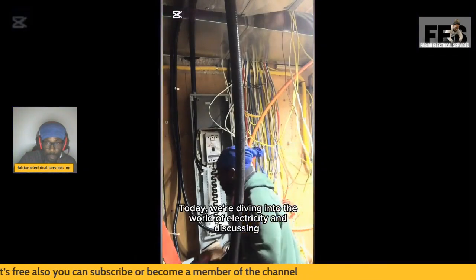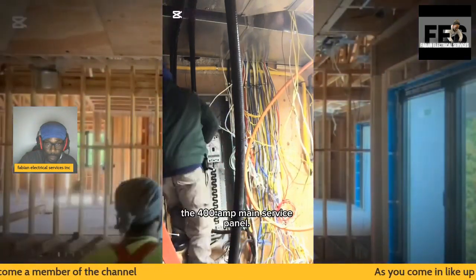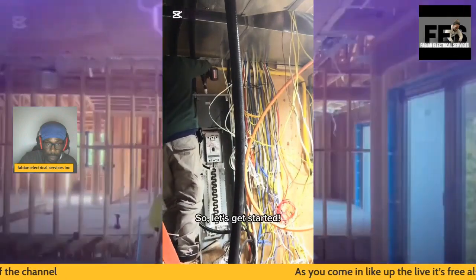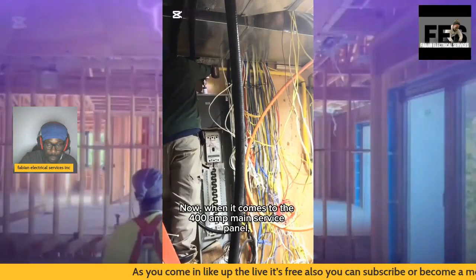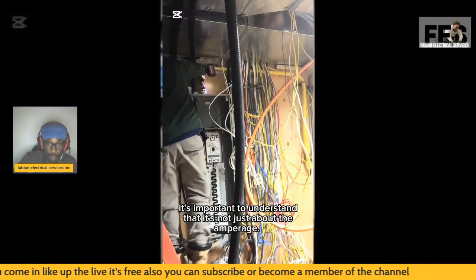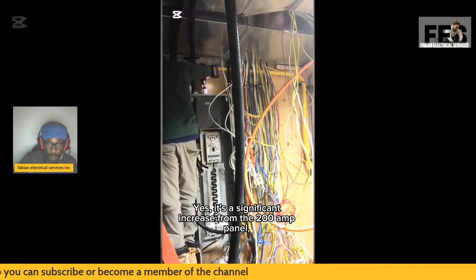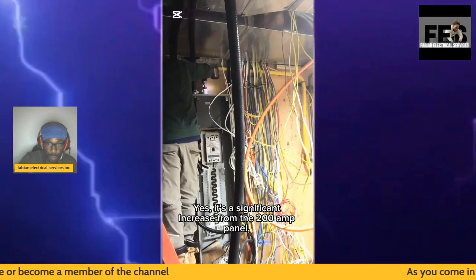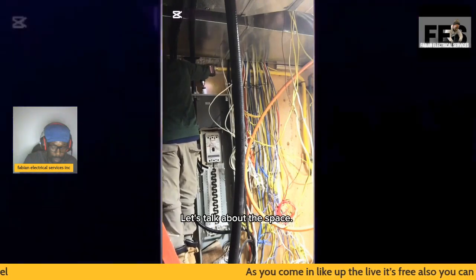What we simply have here is a 400 amp electrical panel, and the installation is going to be the wires, the main feeders coming in, which is 400 amp for the 400 amp service. These are 250 kcmil parallel feeds of cables that I'm running.